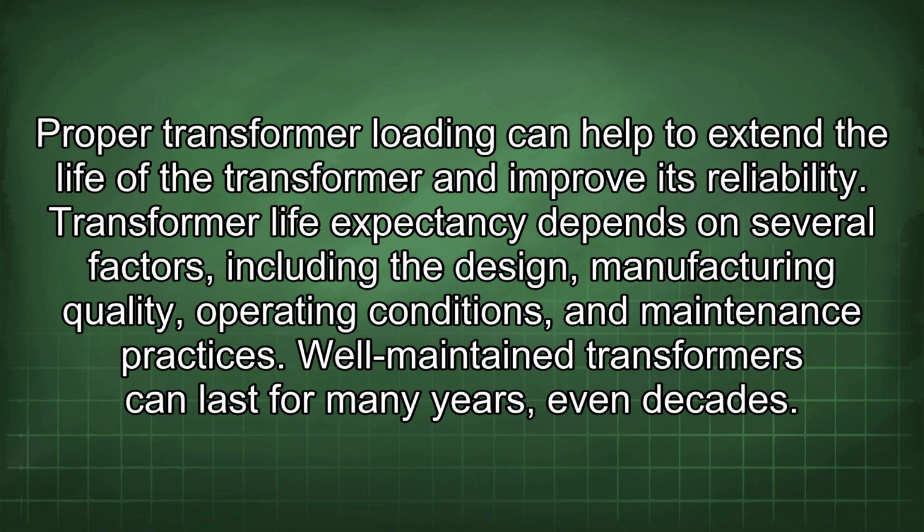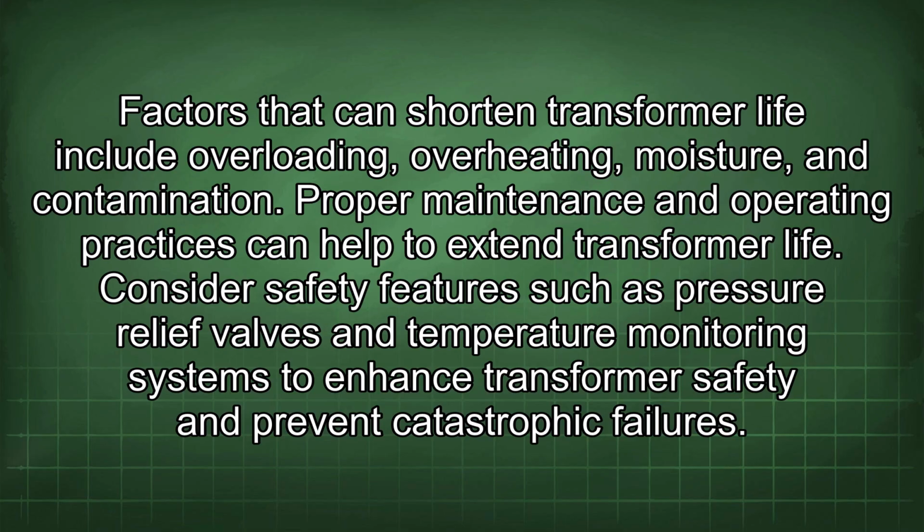Transformer life expectancy depends on several factors, including the design, manufacturing quality, operating conditions, and maintenance practices. Well-maintained transformers can last for many years, even decades. Factors that can shorten transformer life include overloading, overheating, moisture, and contamination. Proper maintenance and operating practices can help to extend transformer life.